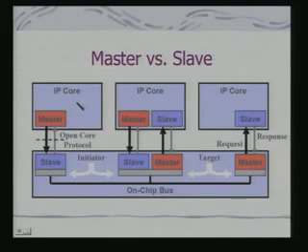So the basic idea, look at this: I have got this IP core. These are different IP cores. This is basically my on-chip bus. These on-chip buses have to be implemented in hardware in terms of signals. But the requests that my master and the slaves would make, these requests or transactions, are defined through this open core protocol. So once these transactions are defined through open core protocol, there is a standardization in the nature of transactions. So try to understand this.